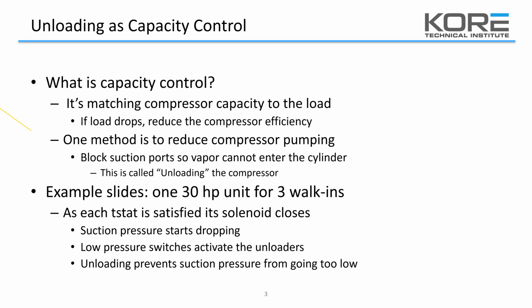It's not the same as shutting off the compressor suction, where the piston is still going to not pull anything, but it's going to compress something. It actually will disengage the cylinder from operating. The gas just kind of goes back and forth between the suction and the discharge reeds, essentially running it in a neutral position.